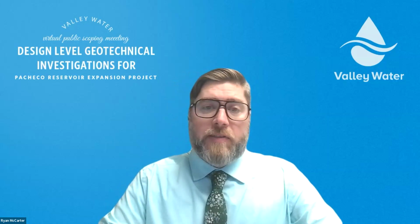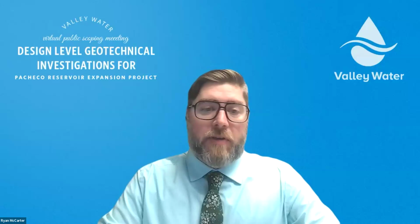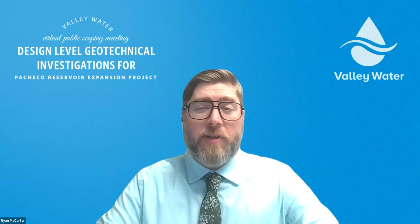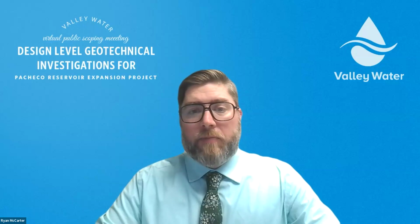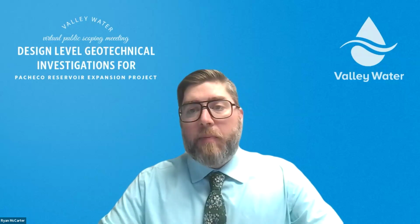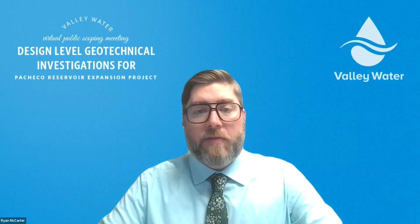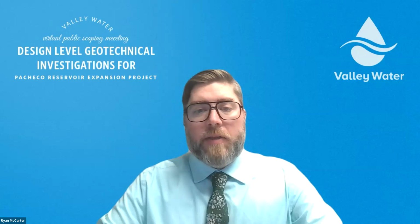But really how that's determined is just in practice in geotechnical engineering. There are guidelines for types of design that require a certain amount of boreholes in an area to characterize it, but it also has a lot to do with the anticipated site conditions. So we can go into a whole diatribe on geology, but sites in the Bay Area have pretty complicated geology. So we are looking at quite a few boreholes here to hopefully gather the information we need. But that's been a pretty elaborate process of review and analysis, looking at different cross sections of the area and what we need to find out and confirm underneath the surface.